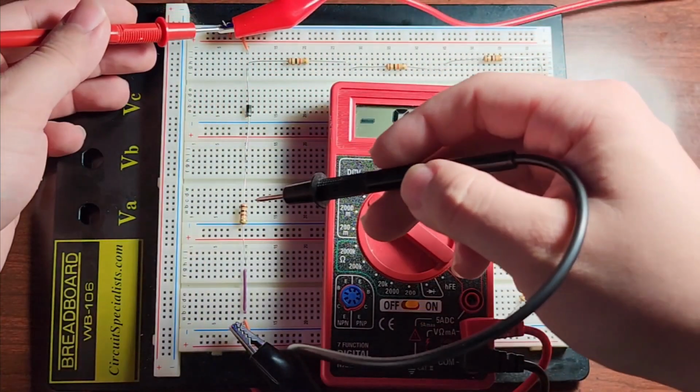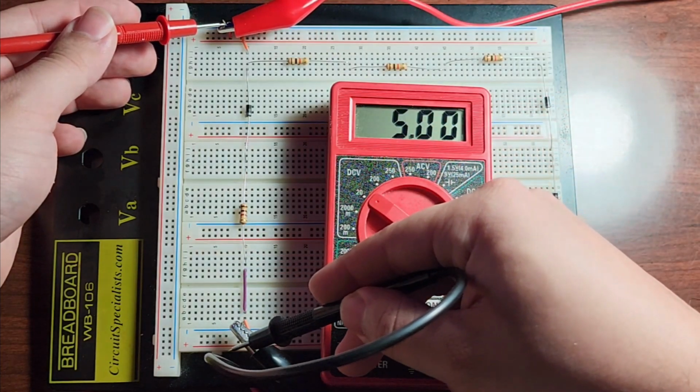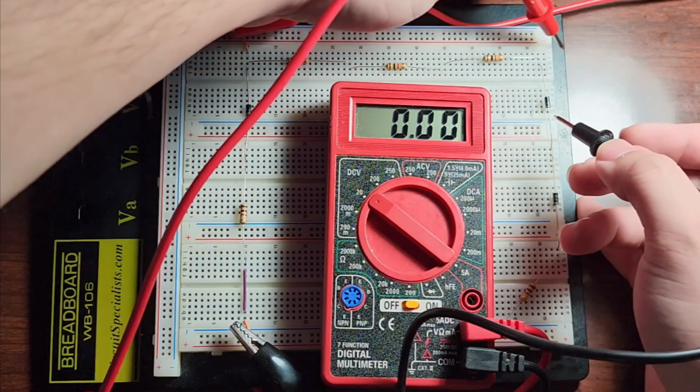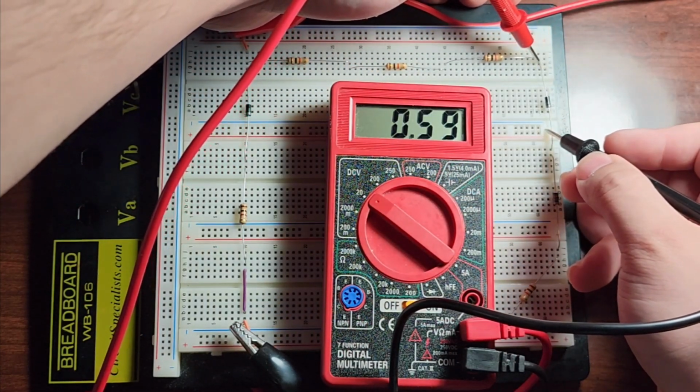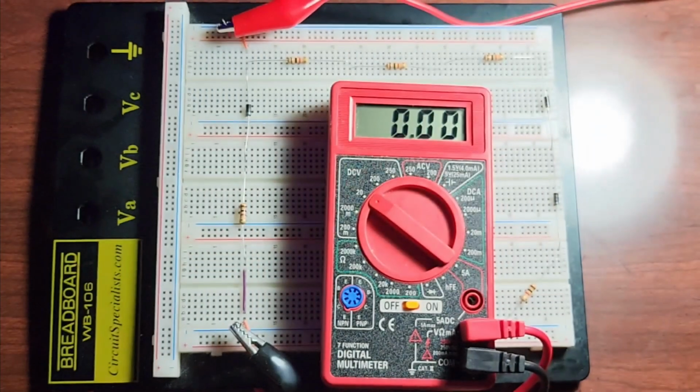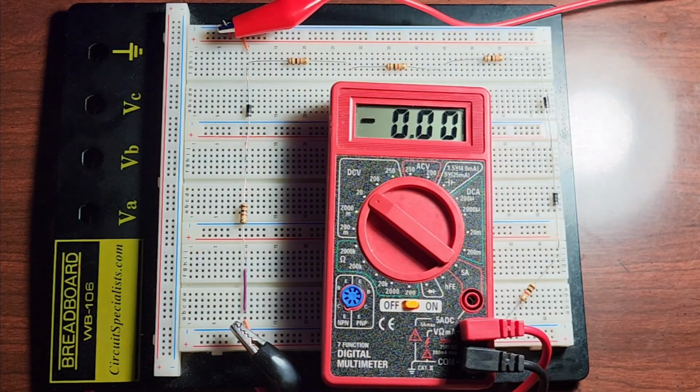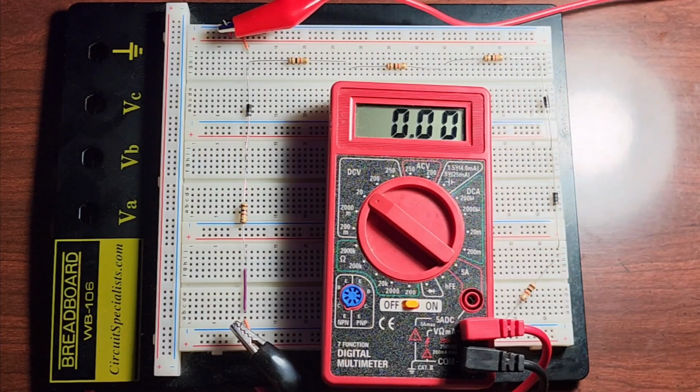And just to make sure here, actually, I'll read the value for the voltage. So we have 5 volts across. And now we have about 0.6 voltage drop. Okay, so what you'll see in a practice problem, if you're given something like this, is your VD0 instead of 0.7 will be 0.6. Now, we noticed while we were doing our analysis on paper, Vin has to be greater than or equal to 1.4. That's twice the voltage drop across the diode. So our Vin will have to be at least 1.2 for this circuit here at 5 volts input.